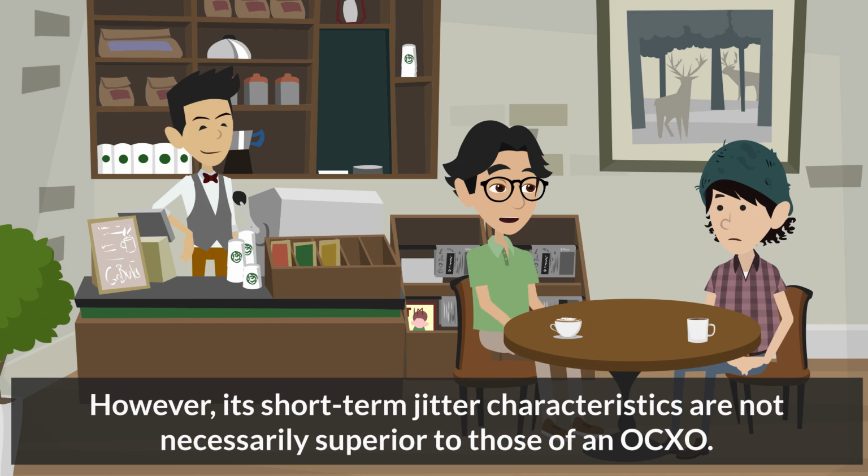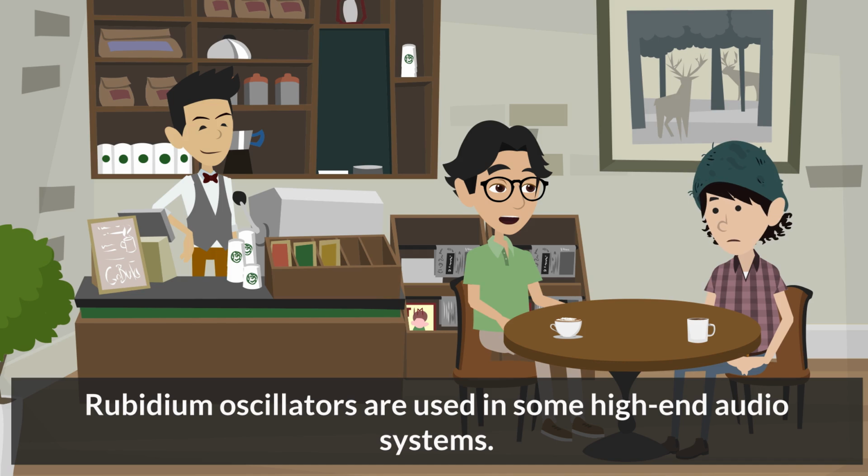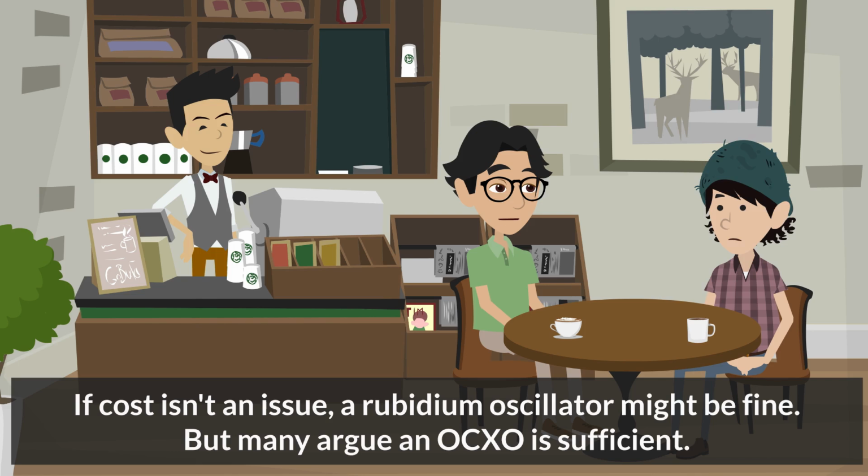However, its short-term jitter characteristics are not necessarily superior to those of an OCXO. It is expensive, large, generates significant heat, and is often excessive for general audio equipment. Rubidium oscillators are used in some high-end audio systems. So you're saying a rubidium oscillator isn't necessary for an audio clock generator? If cost isn't an issue, a rubidium oscillator might be fine, but many argue an OCXO is sufficient.